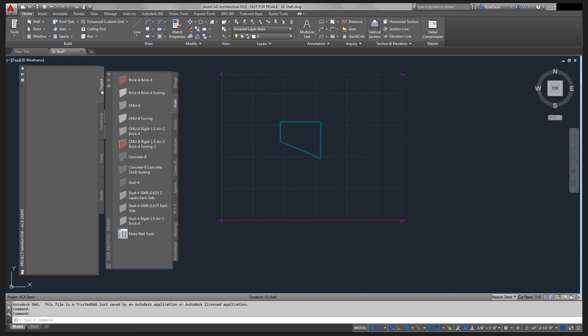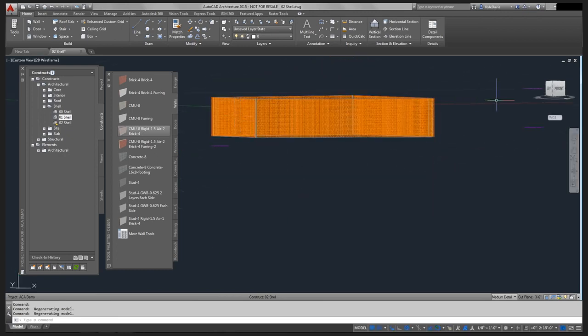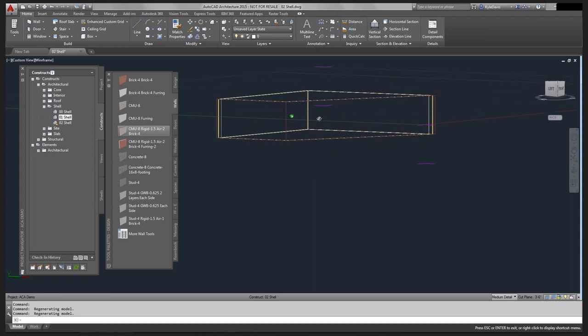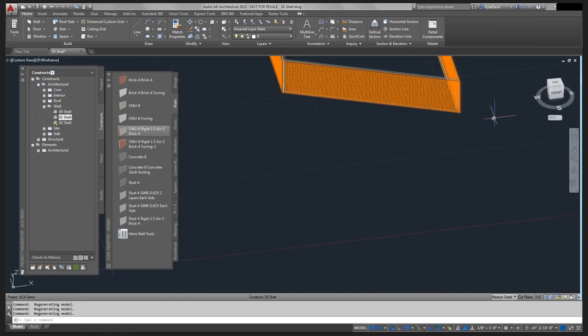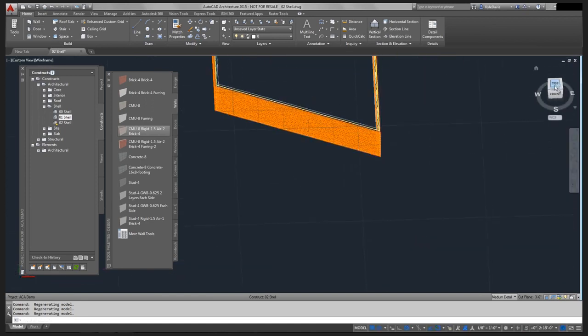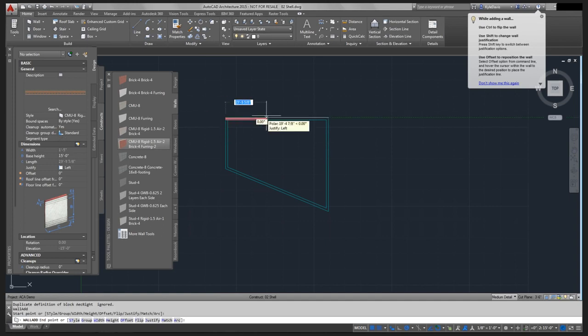And since my project was set up with these elevations and levels, the Project Navigator and Project Browser set up the drawing so that when I come into my level 2 drawing and XREF in level 1, it's automatically below my reference plane. So here you can see my walls touch the reference grid here where level 2 will start. This makes it easier again to make sure that your walls are sitting directly over top of your levels below and above. So here when I'm in level 2, I'm going to go ahead and draw the same thing.